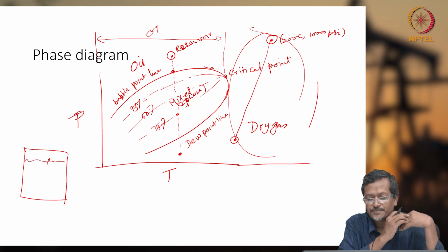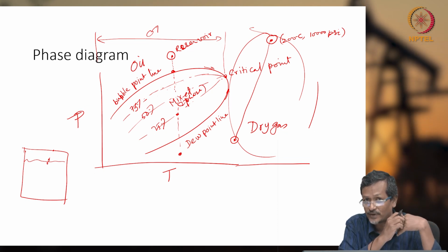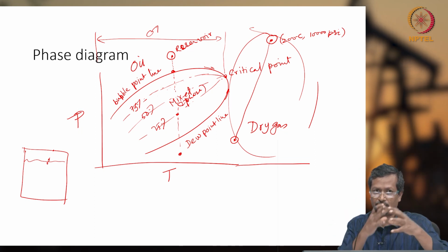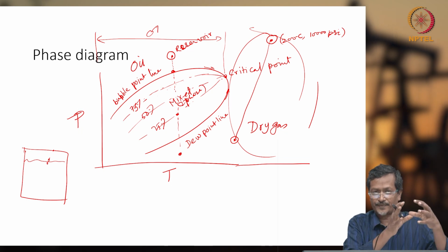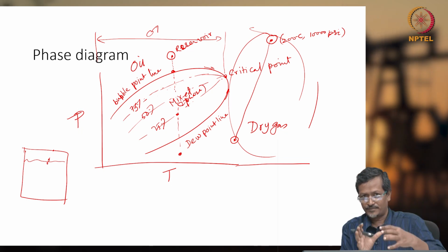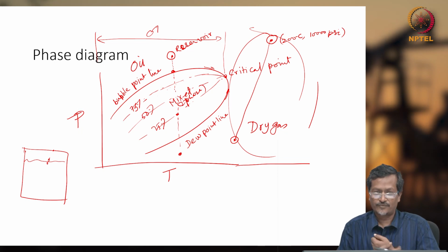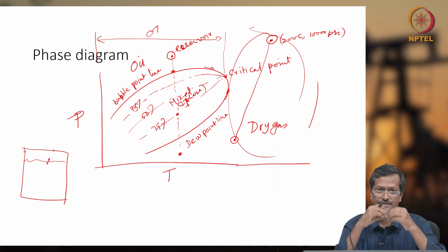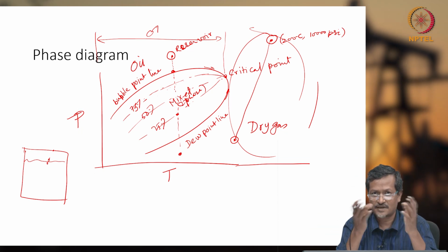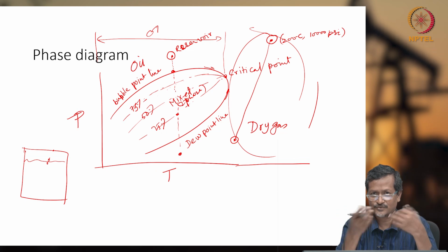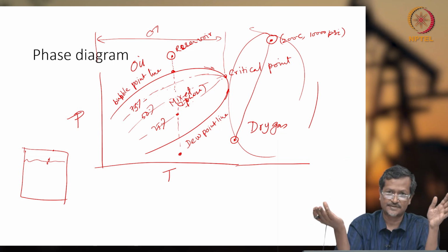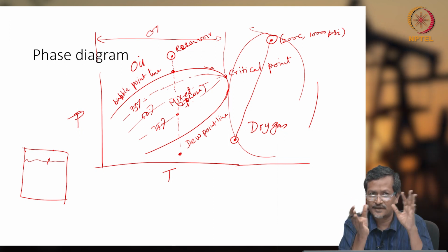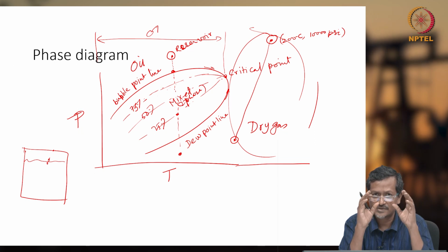So if you change temperature and pressure, the phase will change. You may get, at a certain condition, oil, at another condition mixed fluid like bubbles of oil and gas, and pure oil or gas mixture. From reservoir to surface, you have to check whether it is becoming two phase or single phase. If it stays single phase, that means it is gas and there is no liquid: it was gas, and at surface also it is gas. But when the phase is changing, the situation will be different. Then for handling, you have to consider many factors before selecting any artificial lift.